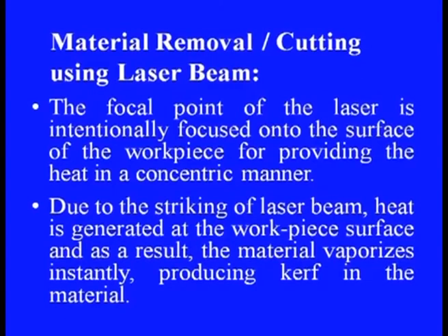The focal point of the laser is intentionally focused onto the surface of the workpiece for providing the heat in a concentric manner. It means the focal point is the point where we want to make a cut or make a hole, in case of drilling. Due to the striking of the laser beam, heat is generated at the workpiece surface. As a result, the material vaporizes instantly, producing a cut in the material.